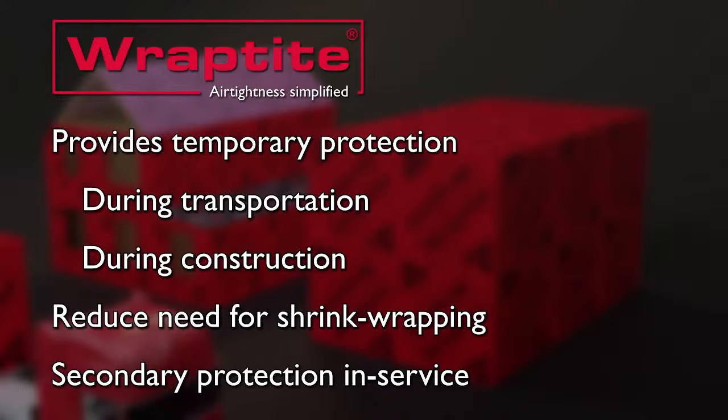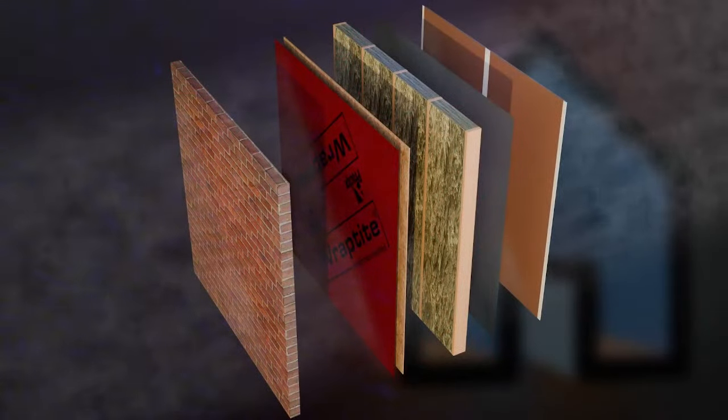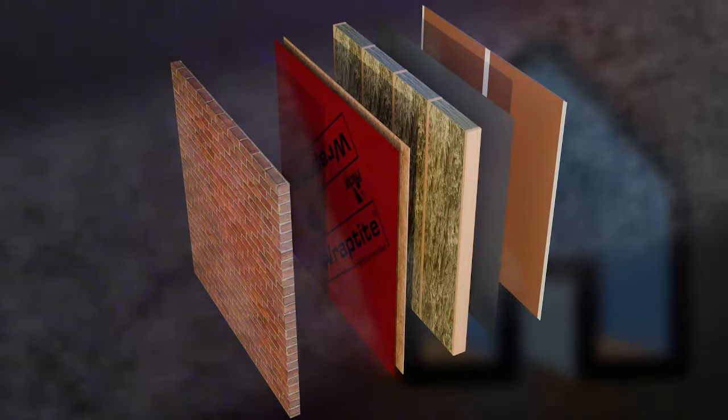This secondary protection can also be useful should the outer covering become damaged, such as slates or tiles being blown off a roof. In this case, the membrane can provide a temporary level of weather protection until repairs can be made to the outer roof covering. The permeability of these materials is important, as it means that protection from external moisture is provided without inhibiting the drying out of moisture from internal sources.